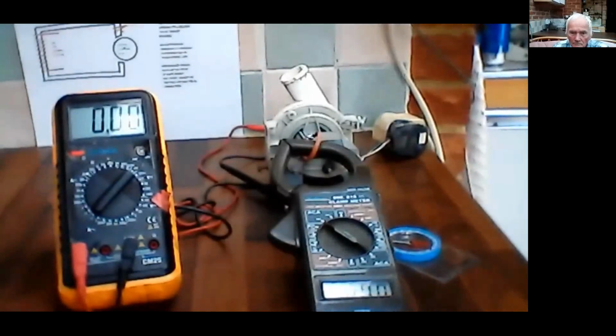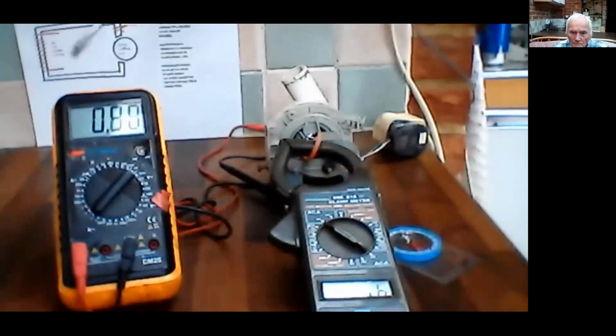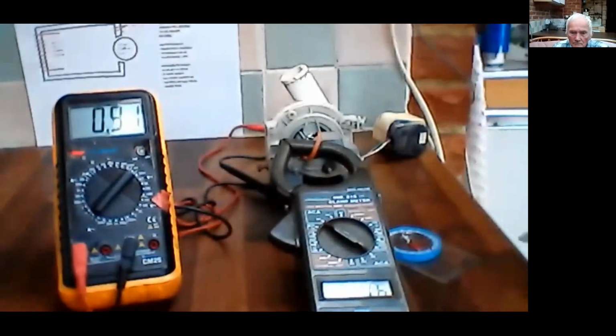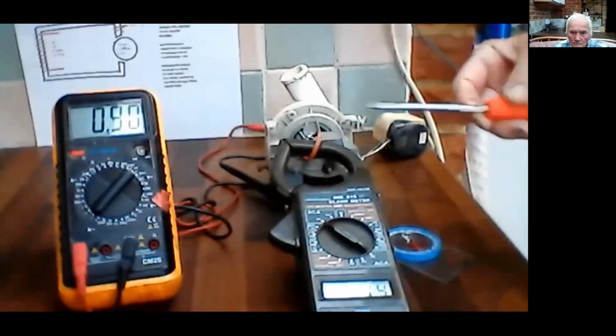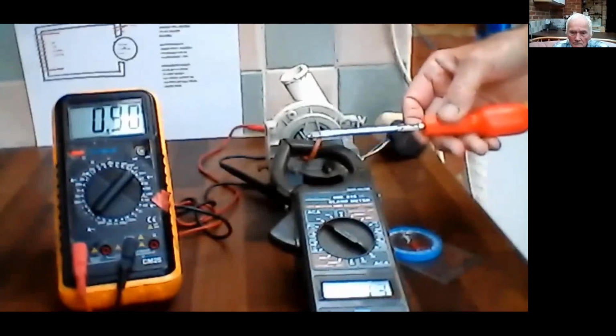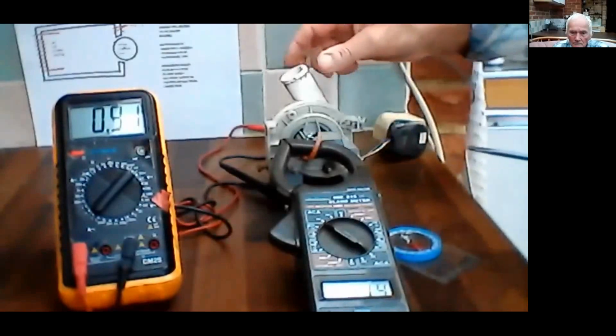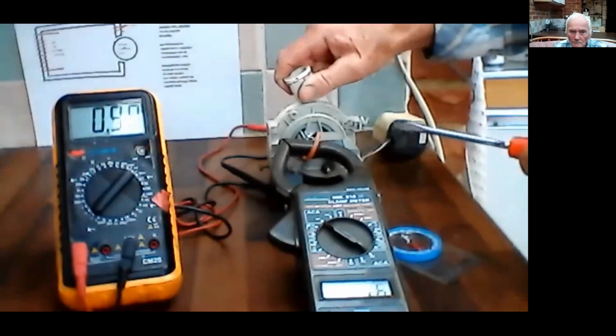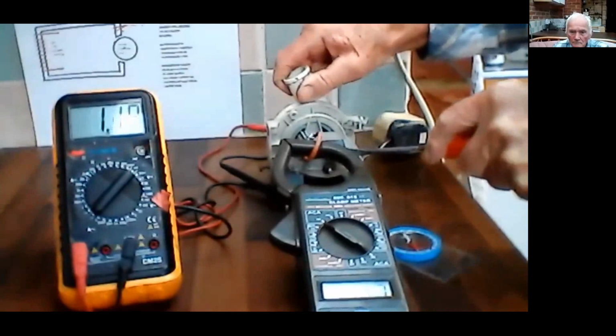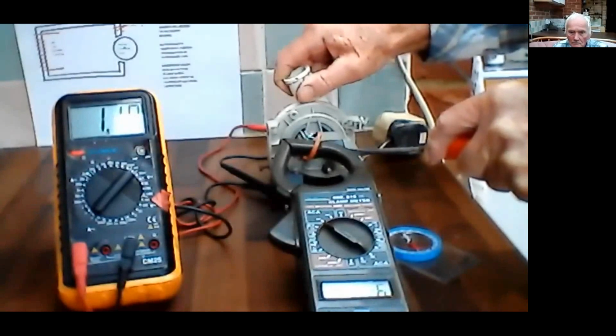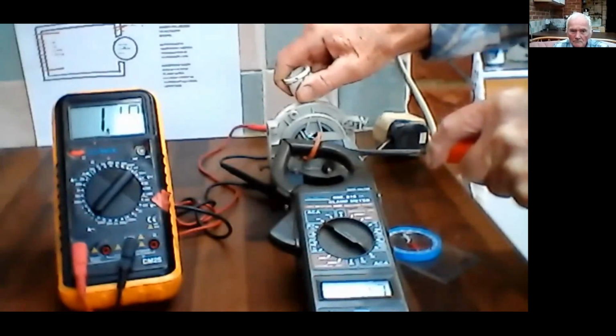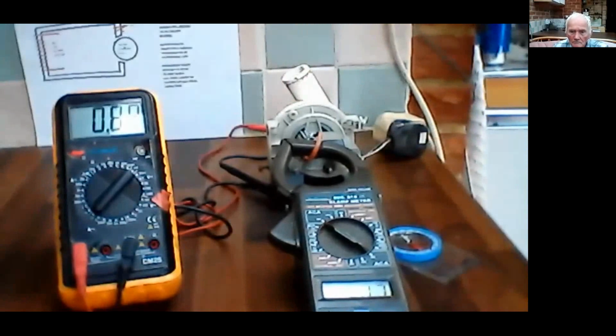So we switch on the motor, and immediately get about 0.9 amps on the primary winding and 11.5 on the secondary, or the teaser winding here that's making it soft. If we now jam the motor, then up goes the secondary to about 12 and about 1.1 on the primary winding. But let me now unplug it.